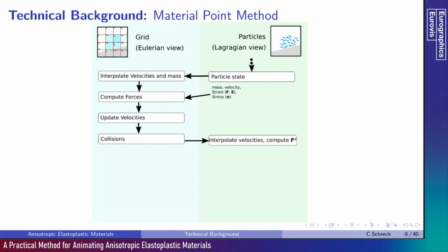We can then apply a constitutive law on the particle. This law is going to define the physical behavior of the material. In our case, we use an elastoplastic law, where the elastic and the plastic behavior are separated into two different steps. First, the elastic stress is computed from the deformation. This can potentially put a particle in a physically unfeasible state, in which the material should break or deform plastically.